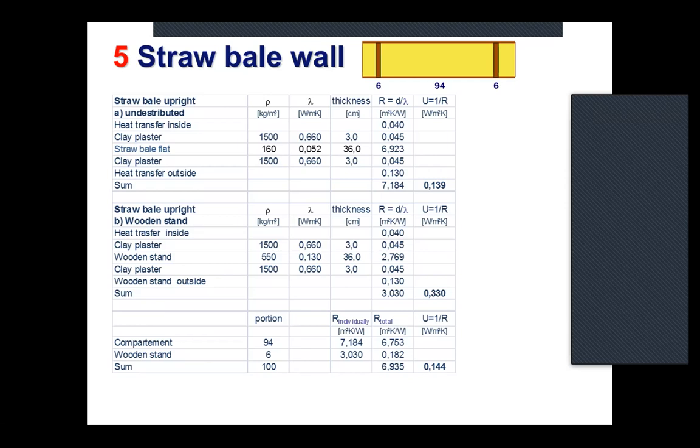You should not calculate when your requirement is a U value of, I don't know, 0.15, so you should not have in your calculation 0.15, but you should have 0.14 or something like that, because there are some real-world things which are not always included in the calculation. So some extra portion to be on the safe side.